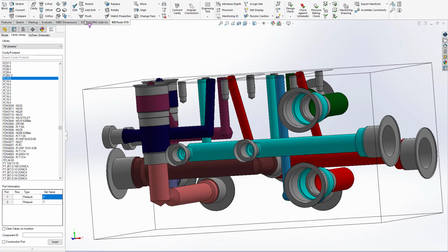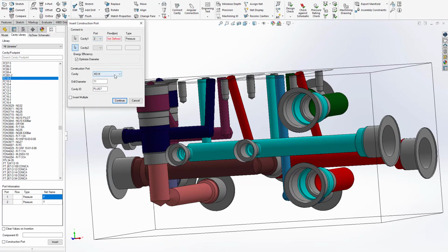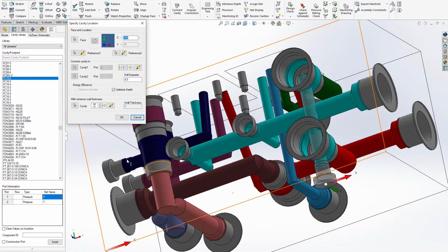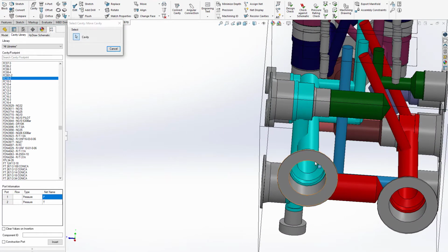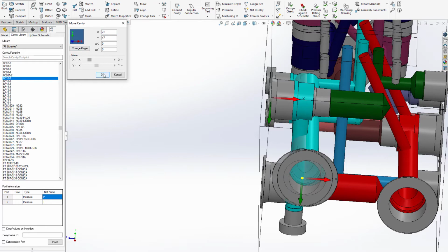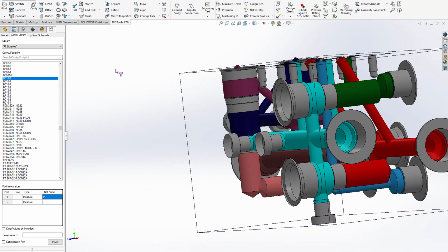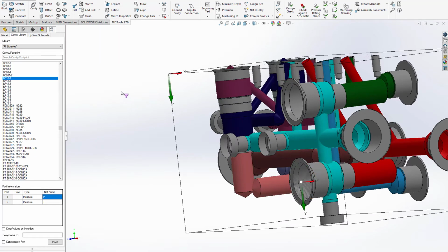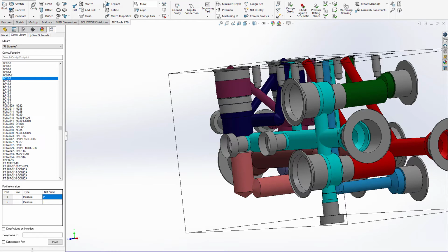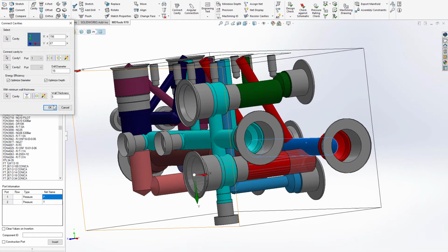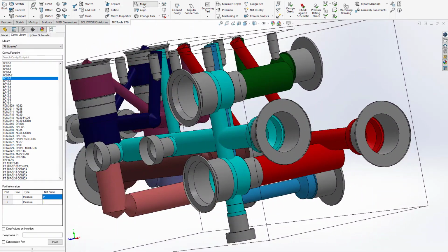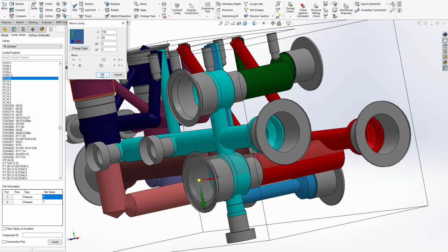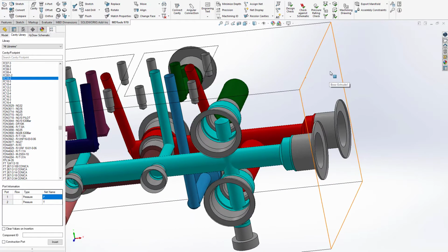Create a construction port between RV2 and T. Position on bottom face. Stretch right face to reduce block length.